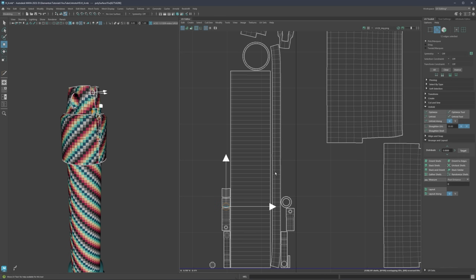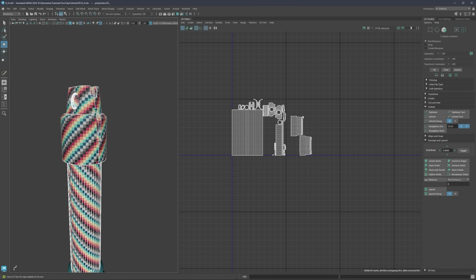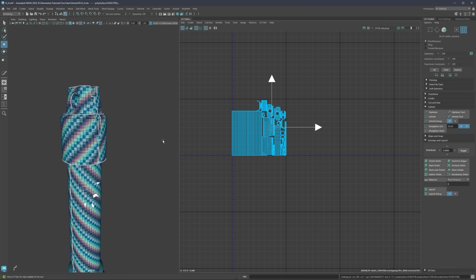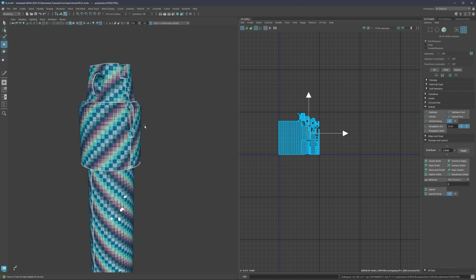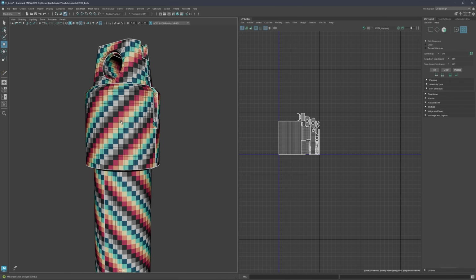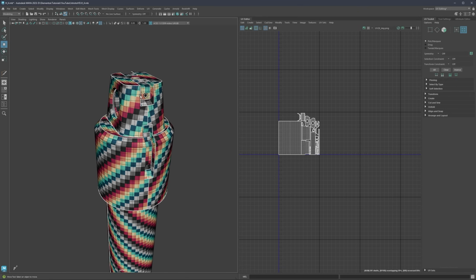So the same thing is going to be here for this one. Let's say just straighten shell, and then we're going to select everything one more time, right click, UV shell, and lay it all out together one more time. And then basically this is going to be your general workflow for creating cuts, creating seams, unwrapping or unfolding, laying out all together, and just in case you need to straighten something or reposition it slightly better. And yeah, basically that is all.